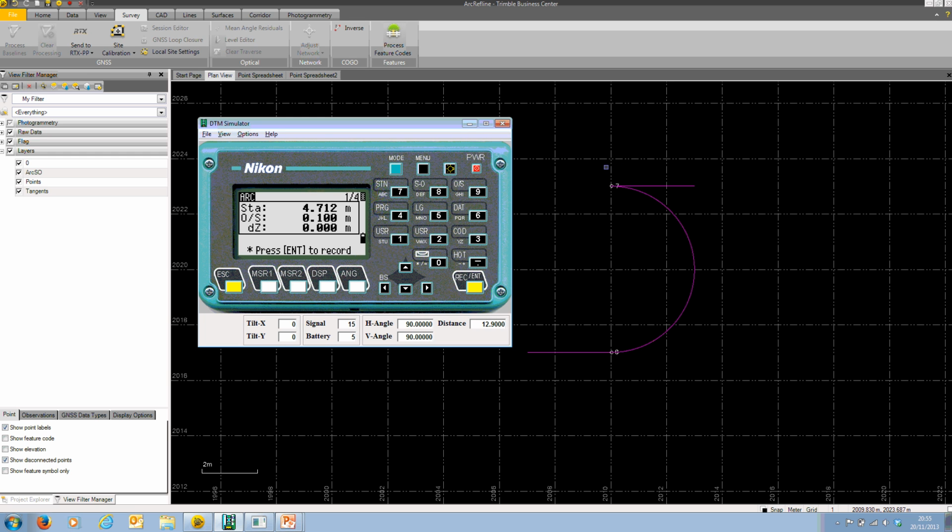So let's try that. So I'm going to change the measurement values here to affect that measurement with the simulator. In this case, I need a measurement horizontal angle of 68 degrees, 11 minutes and 55 seconds, measuring a distance of 10.770 meters.